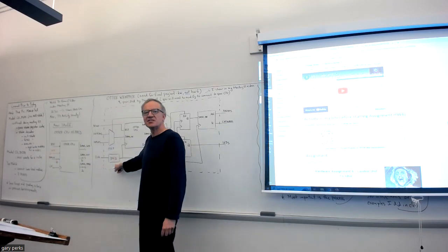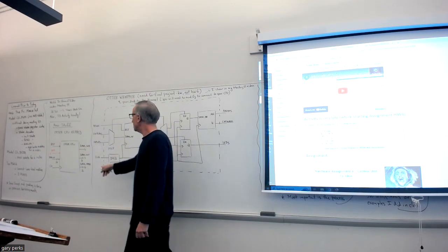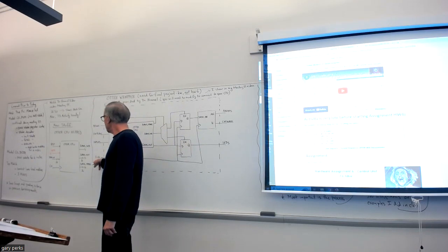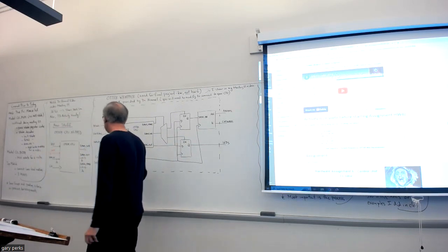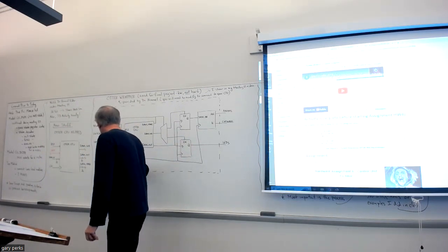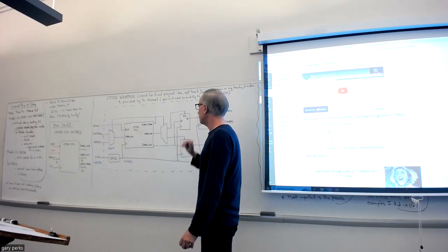Okay, you've seen something like this, a divide by 2 for the clock. Right, you see that in CP133. We talked a little bit about this, and this is covered in CP133. What's the clock frequency of the Basys 3 board clock? That's 100 megahertz. You see we're dividing that down by 2, so 50 megahertz. Here's the output, and that's what operates our Otter CPU as well as